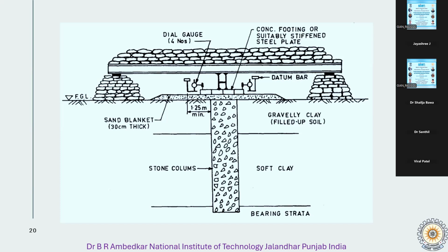the load test is continued for 10 to 12 mm settlement at design load for the single column test, and 25 to 30 mm settlement at the design load for a 3-column group test.